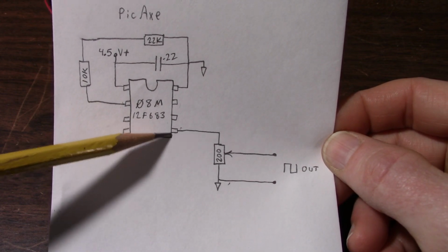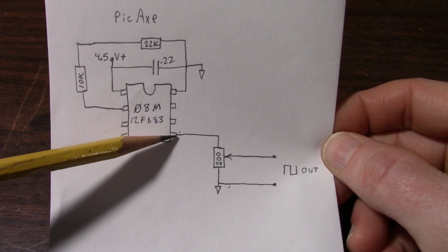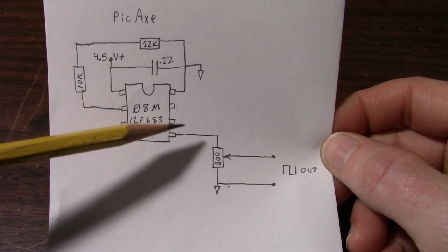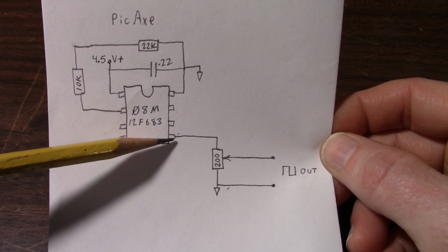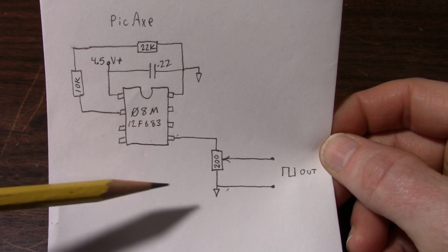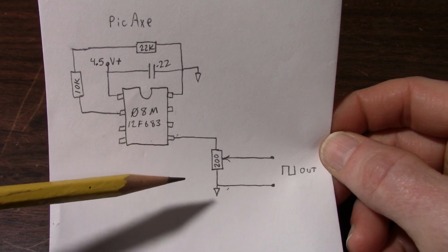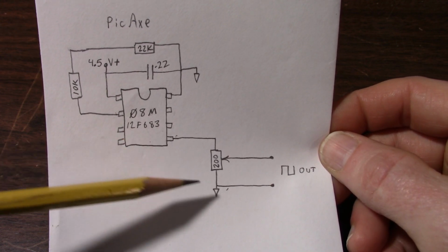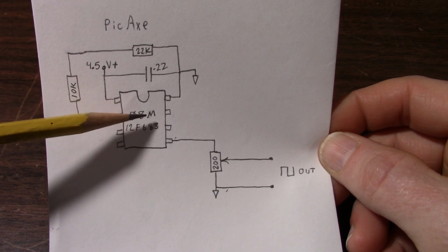This pin has several functions, and one of the functions is a pulse width modulated output. So with one line of code, I can turn that pulse width modulated output function on, and by putting some numbers in, I can set the frequency and the duty cycle. And the PWM is separate from the microcontroller circuitry in here.